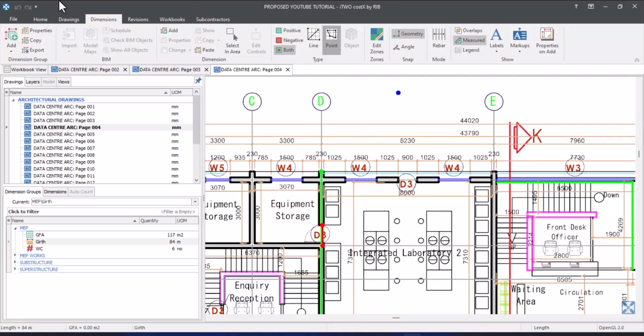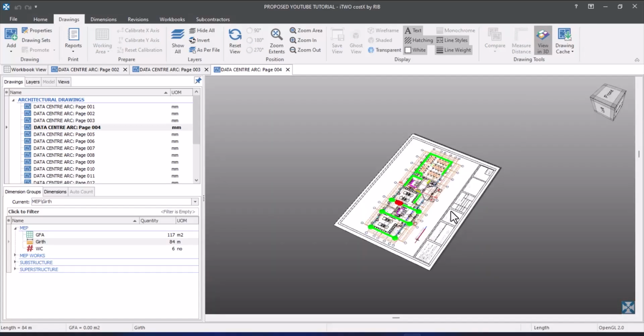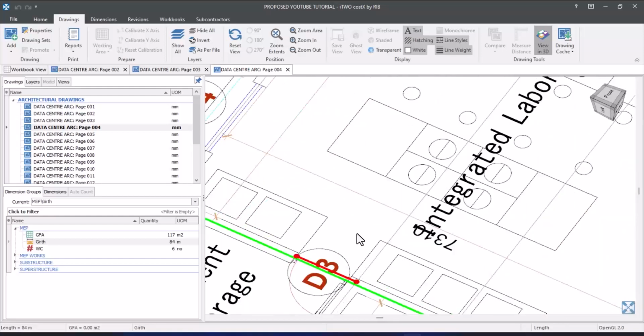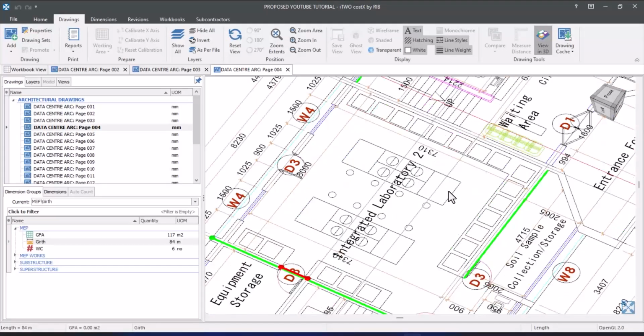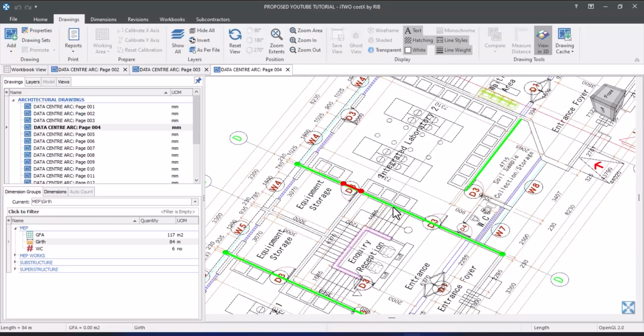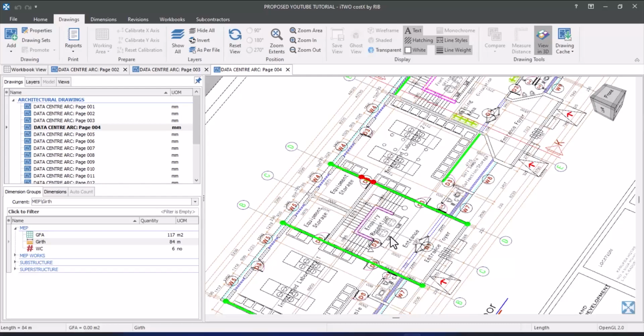You can see, when I go back to my view in 3D, which I said I'm going to show you later on, I view it in 3D. But the reason why it is like this is because I did not add the wall height. So the moment I add the wall height, it's going to show you the real 3D form of this takeoff that we did. When we get to block work, I will show you how to add the height and also do some other advanced takeoffs. So let's go back to floor plan.